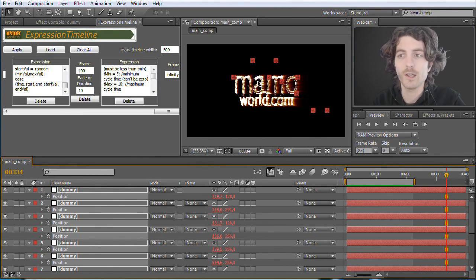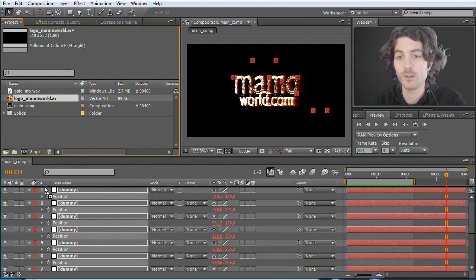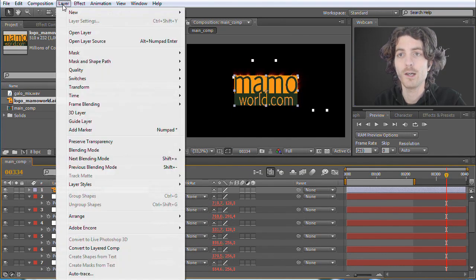of your logo. And if you have something like a mask or already from your text, you can use this directly. But I'm also going to show you what you can do if you have just an image and no paths available. So what you can do is use the auto trace tool. In case you do not know it, I just show this. So I drag in here my logo from which I want to generate the path, and click on layer, auto trace.